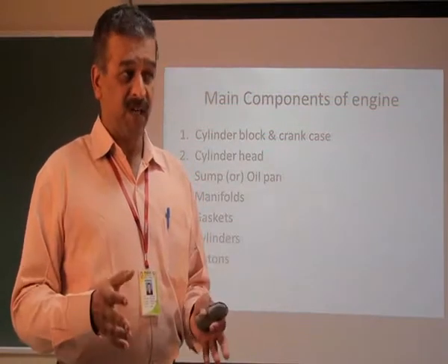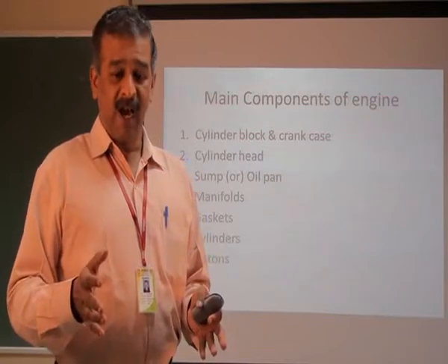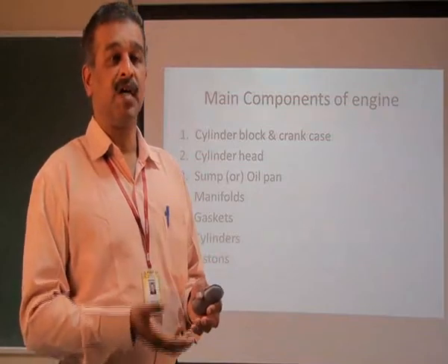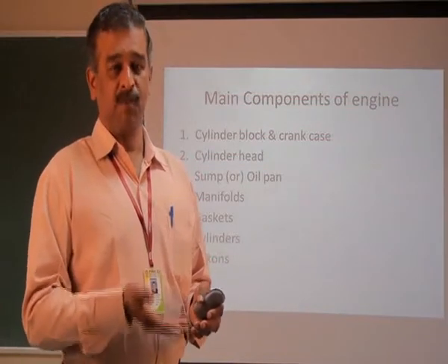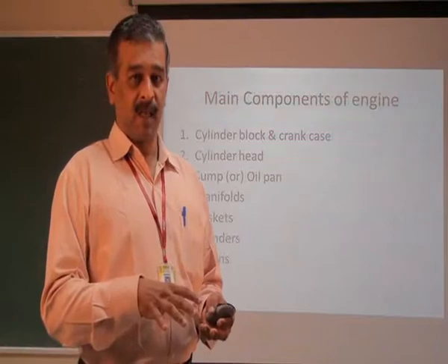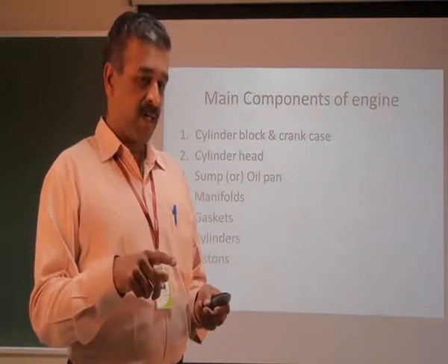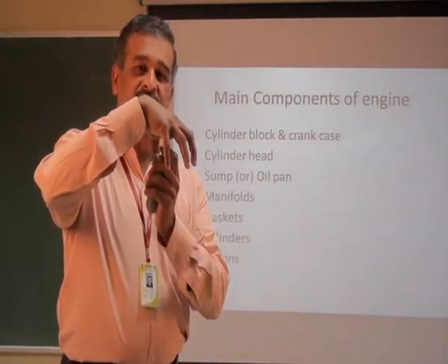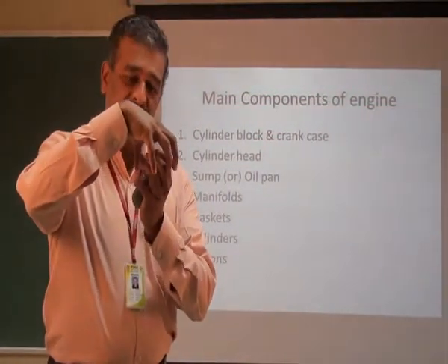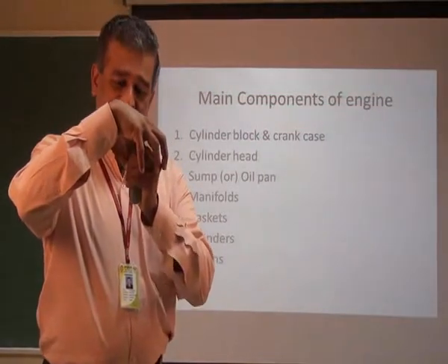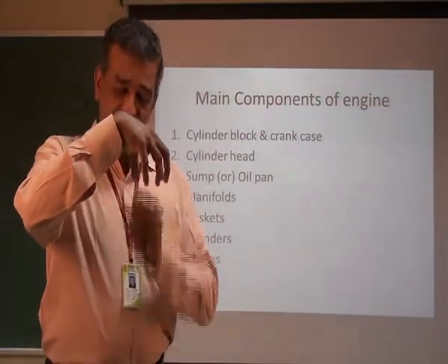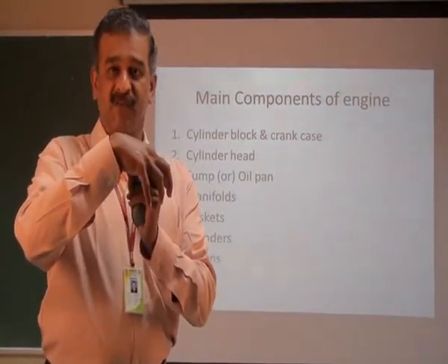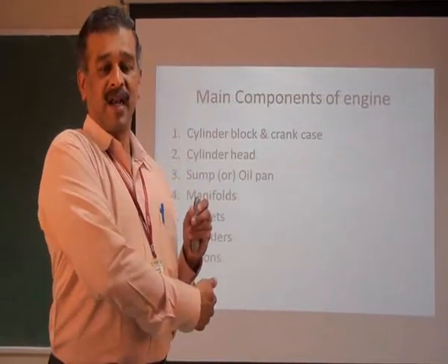So it should be very hard enough to withstand all these things, and all the sides are closed. Only one side is having a moving component, which is called the piston. So it is having a closed container and a moving part. Inside this closed container we are going to fire the fuel, and at that time the piston will be pushed down. This motion is transferring the power from the blasting of the fuel to the crankshaft.